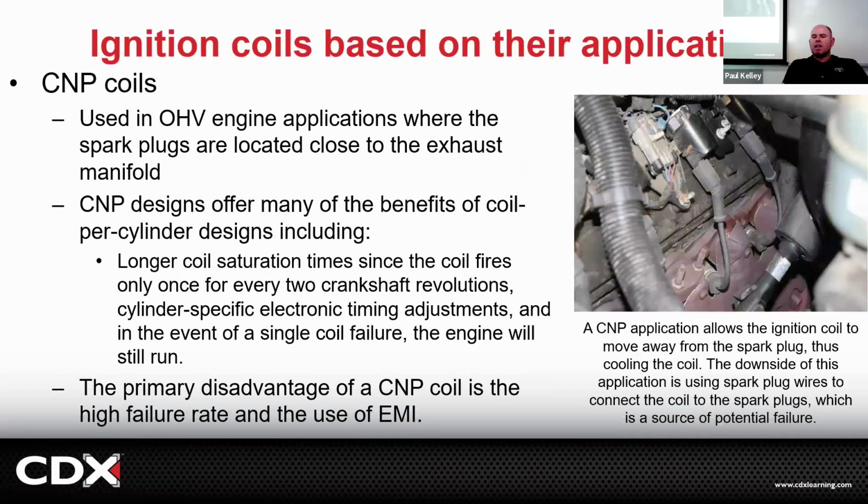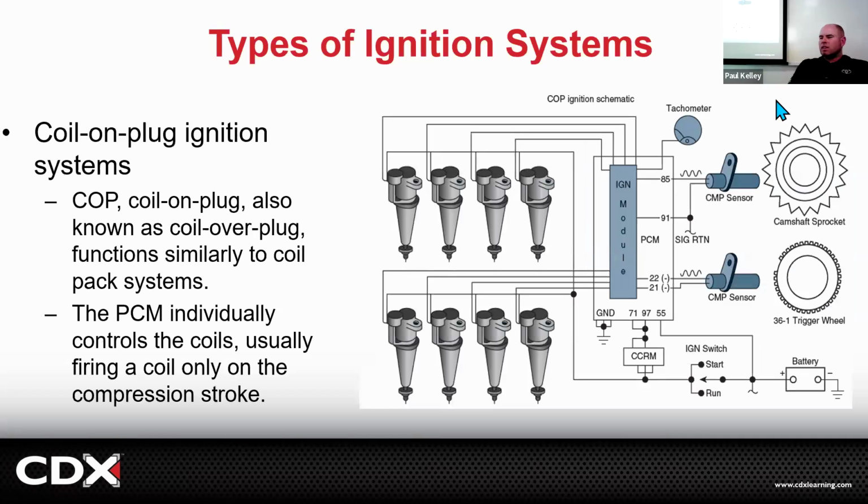But now, when you got this system, there is no tune-up. These coils don't have a maintenance interval. These coils don't need to be changed at 100,000 or 120 or 150. They get changed when they're no good. So we don't do this as a maintenance. We don't do sensors as a maintenance. The only thing we do on a maintenance on this one is the spark plugs. And you'll see if this has an iridium coated spark plug, that's like 120,000 miles.